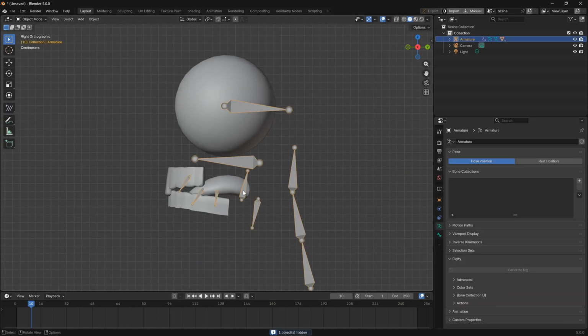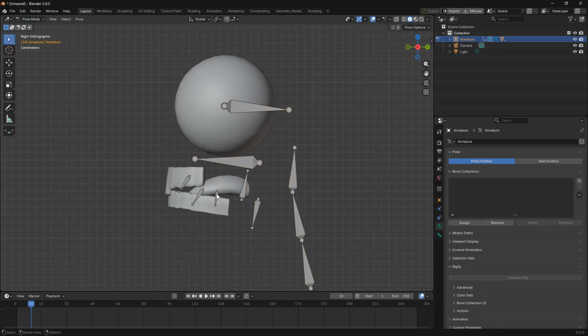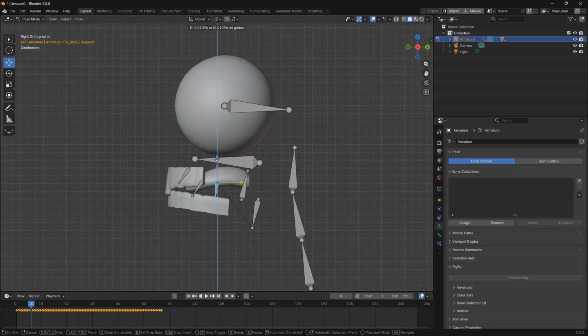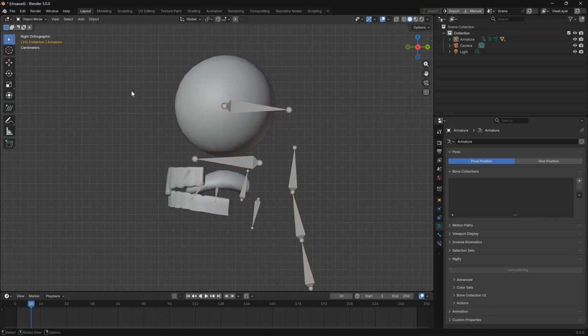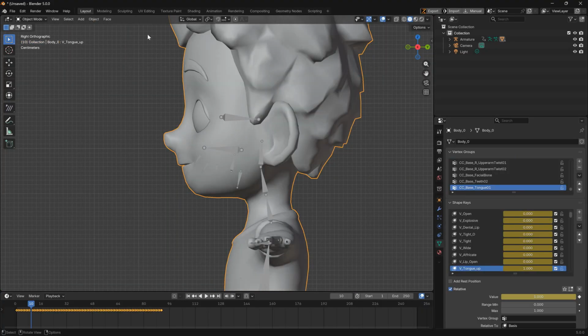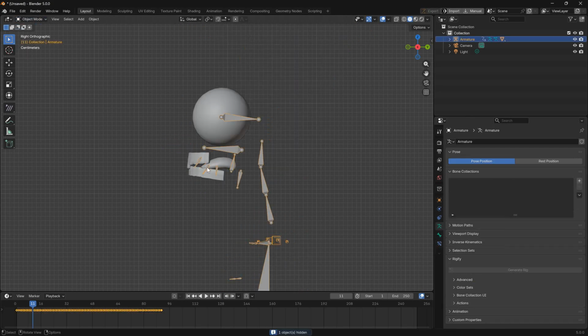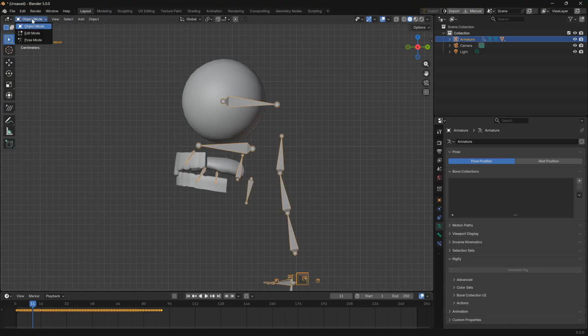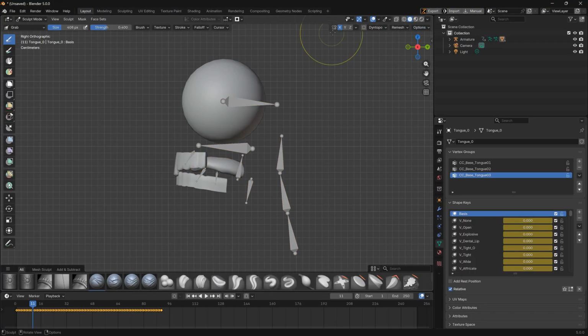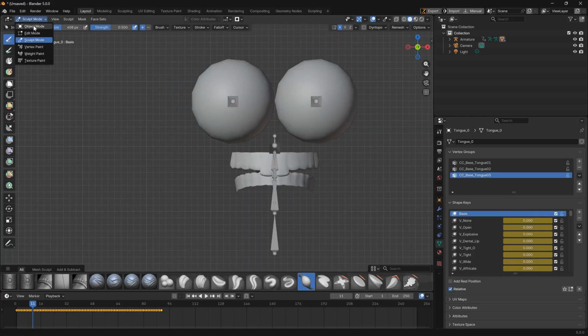You don't have to sculpt them in sequence. You can just click the star button below the shape key. The star function will both isolate the shape key, meaning that only that can be active, and it will also allow you to sculpt on it. Alternatively, you can manually dial it to 1 and then sculpt on it, and then manually dial it down to 0 after you're finished.